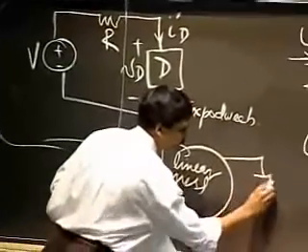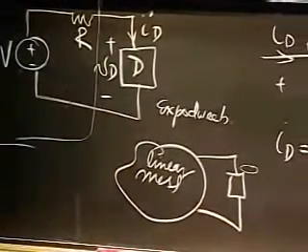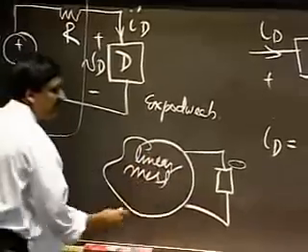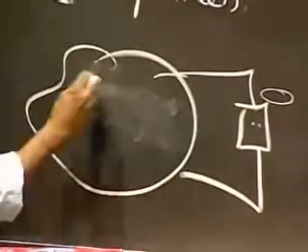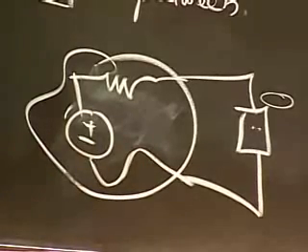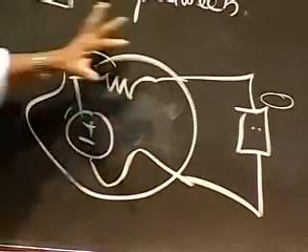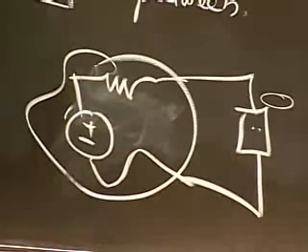The reason we keep looking at this pattern is that whenever you have some big linear mess connected to some interesting device, if all you care about is analyzing the behavior of that device, you can take this linear mess and simply figure out the Thevenin equivalent, or the Norton equivalent if you like, replace this whole thing with its equivalent, and then go ahead and analyze it. So boil an arbitrarily complicated circuit down to a very simple pattern of this sort.